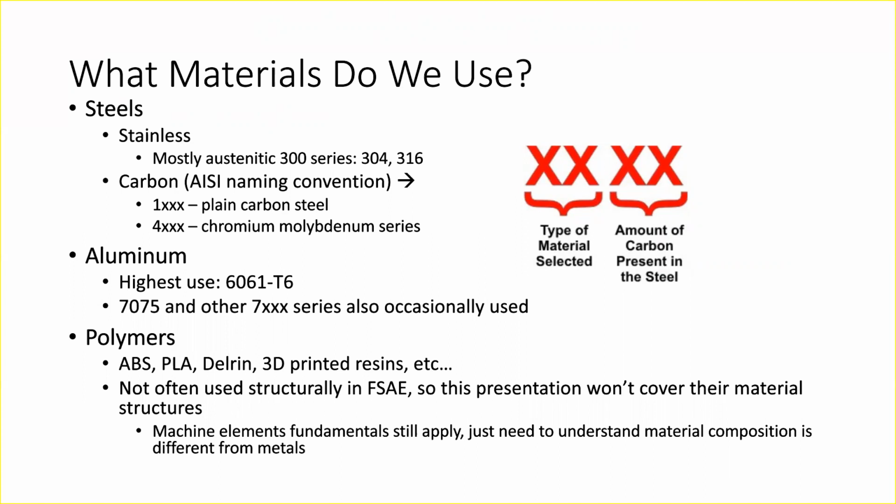If you look at different steels, even though they have different yield strengths, they're still going to be relatively similar in stiffness. So even as they're doped with all of these different metals, the primary constituent is still the steel on an atomic level. So that's why the stiffness remains pretty similar, even for the same type of material with different dopants or different heat treats. So why would we want to heat treat, or why would we want to, I don't know, strain harden a material? The reason is it's a trade-off between ductility or toughness versus hardness in most materials.